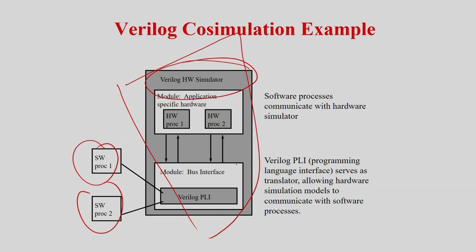But people sometimes also put in some kind of interfaces. They have written some kind of interfaces, that is the software co-development environment. People have written a lot of interfaces in Verilog itself. In that case it will take the software and convert it into some kind of hardware representation so that it can be integrated with this environment. Again, to tell the story from the beginning: Verilog can simulate hardware which is written in languages like Verilog, or there are a lot of HDL simulators. HDL simulators will take the soft version of your hardware and execute it, but they cannot take how a software will run on it.